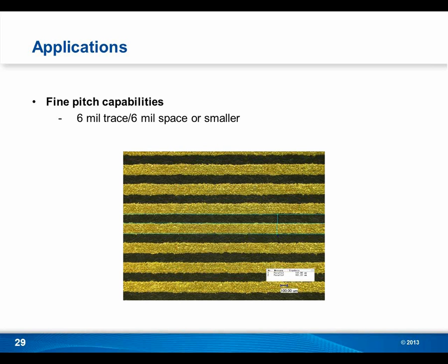Okay, you wanted to get this question from Mark here? Yeah, sure. Mark said he'd like some more information about LDS-compatible 3D printing. So the 3D printing is a process Stratasys is promoting right now. They're actually printing with their 3D printers directly in a PC-ABS grade material, that's an LDS grade type. So again, the part can be made directly in this 3D printing process, which is a great help to get a part and put some circuitry on it right away.